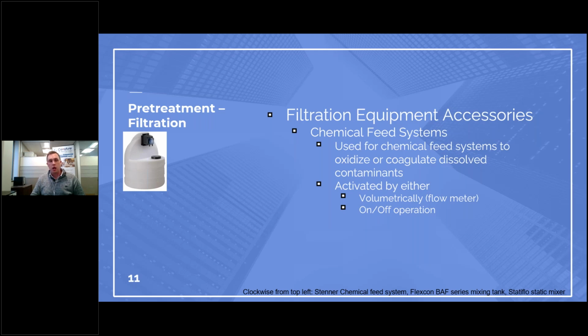And then its job is to dose, whether it's an oxidant, a coagulant, or something of that sort, into the water. So that either you can take dissolved contaminants and make them oxidize, or maybe coagulate some organics together, or maybe you've got another purpose altogether. Maybe you're adjusting the pH. A bunch of different ways you can look at it.